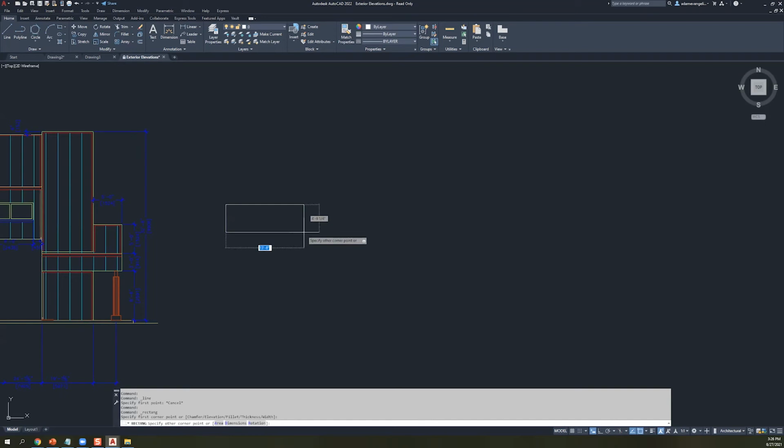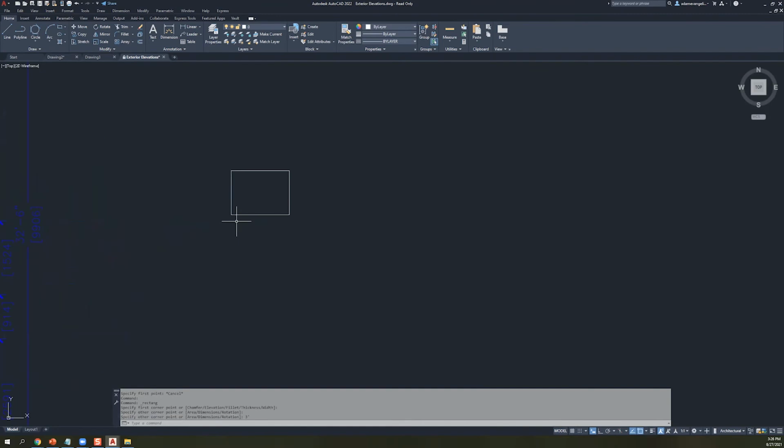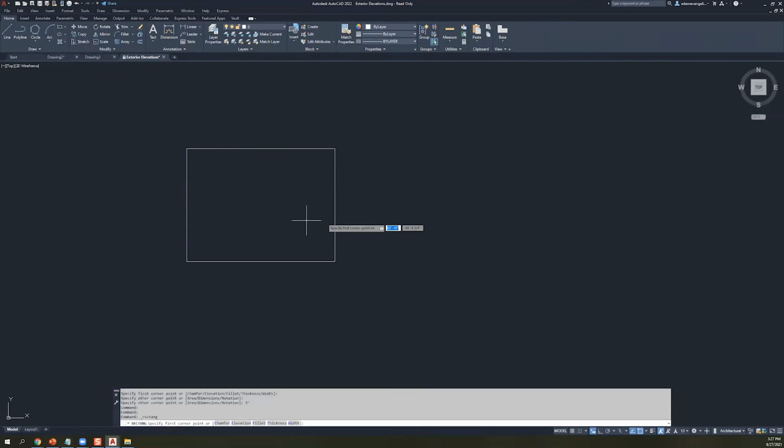So here's what we're going to do. I have the rectangle command selected, and this is going to be a 4-foot by 3-foot window. I used the rectangle tool to simplify that input, and you saw the dynamic input fields where I could tab between them. Noting that if I want 4 feet, I just type 4 apostrophe and that gets me what I need.